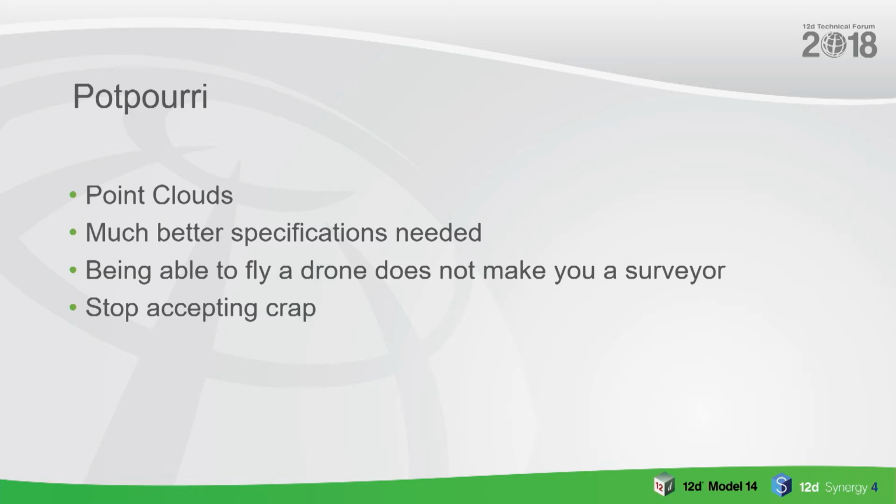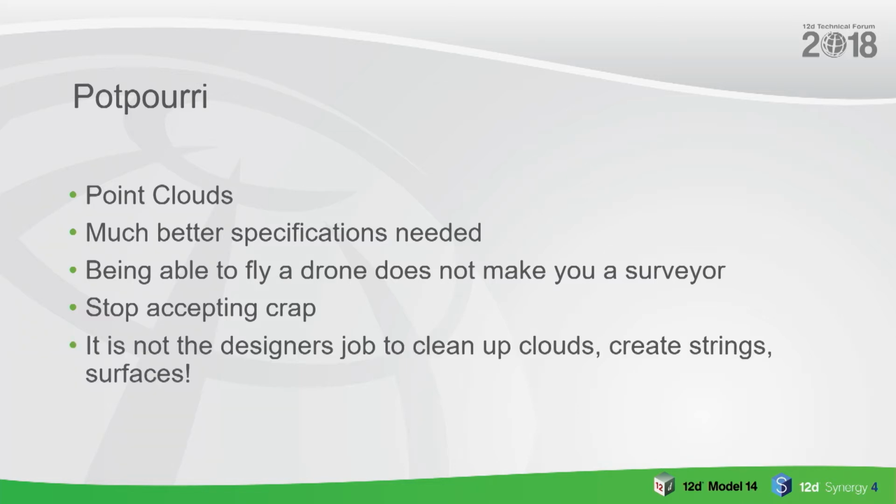They've rounded the Z value to 0.1 of a metre in the processing somewhere. It is mind-boggling. And as I say, it's not up to the designer's job to clean up clouds, create strings and surfaces. That should be part of your specification going, we need this stuff. Don't give us dumb point clouds.